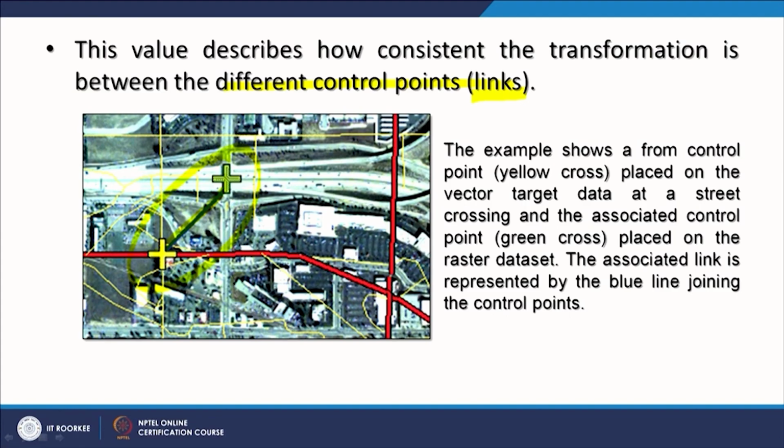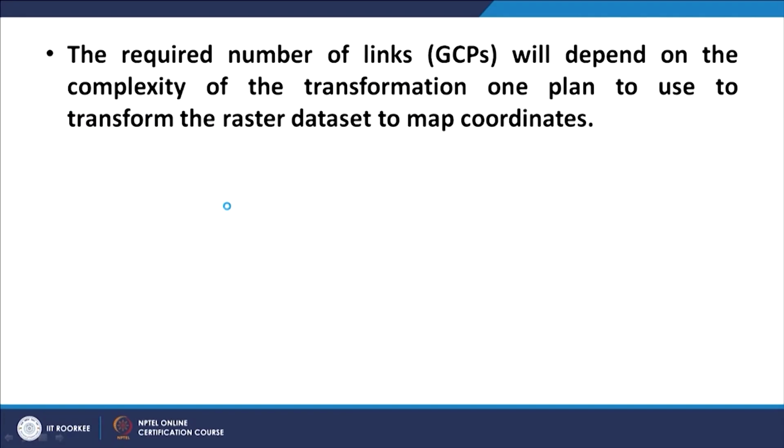So that is why, while doing georeferencing, or this first step, the registration of ground control points of your input image to the master image, whenever you see that any GCP is giving a large error, just remove it and recollect it or go for a new GCP.